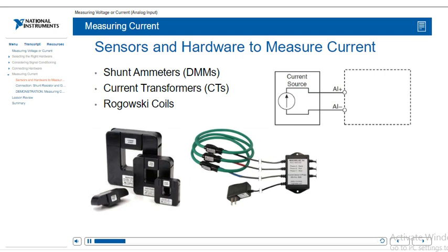So current measurement shunts, or current shunt resistors, are actually resistors placed in the circuit for the purpose of measuring the current that flows across the shunt. These are fairly common electrical components and exist for a variety of applications. When you're sizing a shunt, it will be based on the measurement current range, output range, and power flowing through the circuit.